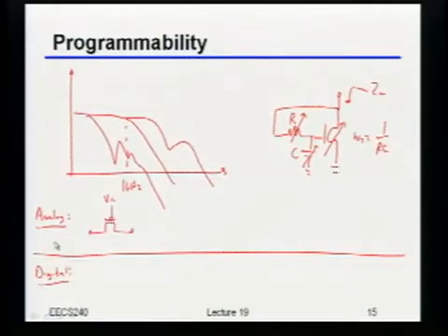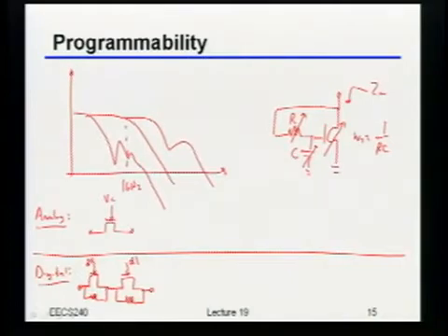But in contrast, if I built this in a digital way, then I might do something like the following. Essentially, I take some big polysilicon resistors. Let's call that D0 and we'll call that D1. I take a string of big polysilicon resistors, and if I want to reduce the resistance, I just turn on a switch that shorts that resistance out, right?